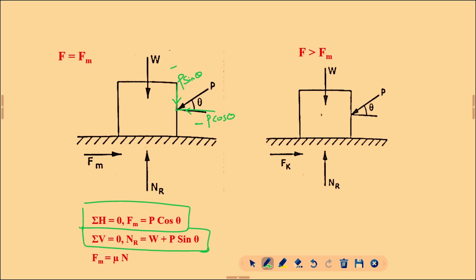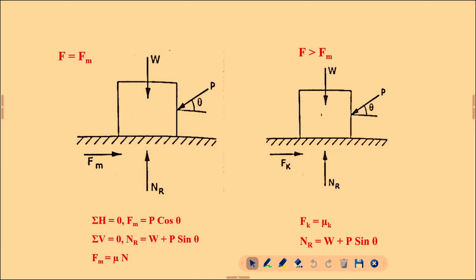And with the third case, this equation we can also apply: the coefficient of friction is nothing but limiting friction to normal reaction. Fine. Then what is the fourth case? If the object starts moving, that is F is greater than Fm, what will happen? Here the equations of equilibrium cannot be applied because the object is in moving condition. So, only the dynamic case we can apply.